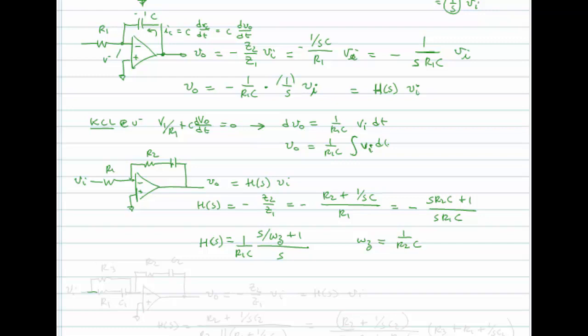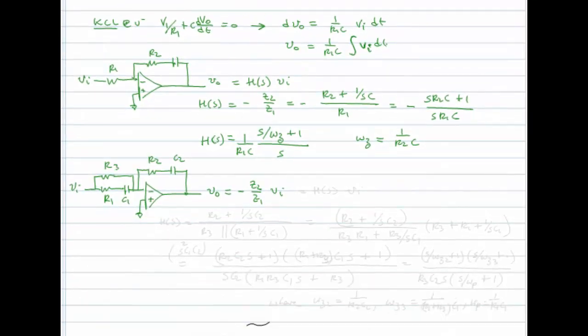Let's take one other example here. What if I had... this can get messy pretty quickly, but just to show you how relatively easy it can be to solve these op-amp transfer functions, simply by knowing the inverting amplifier architecture, whose gain statement is minus Z2 over Z1. I'll have C2, C1, and R3.